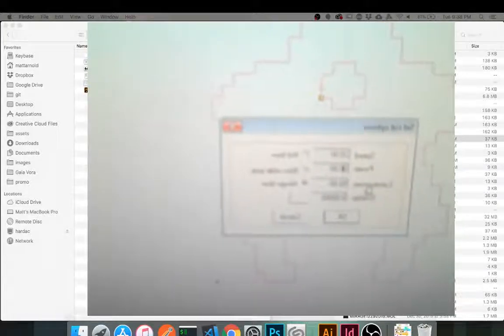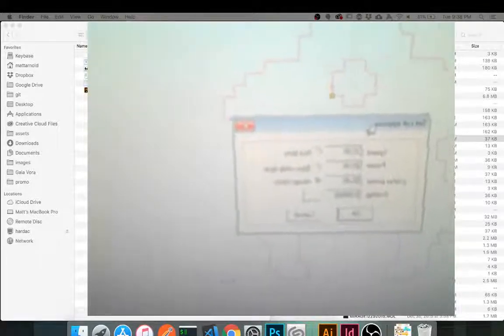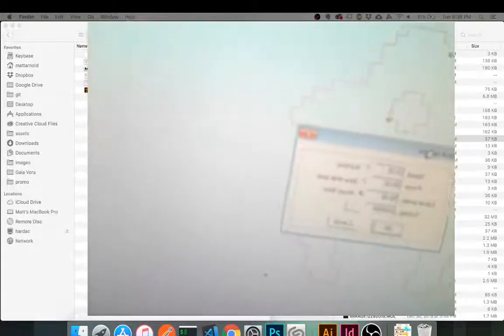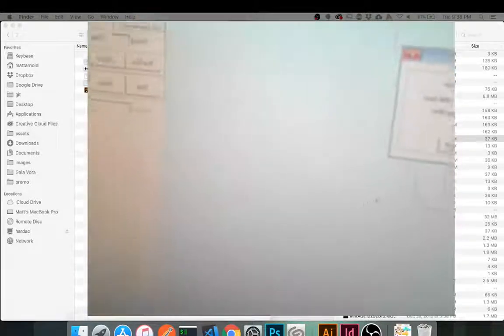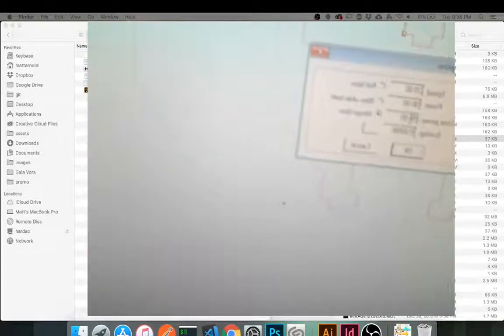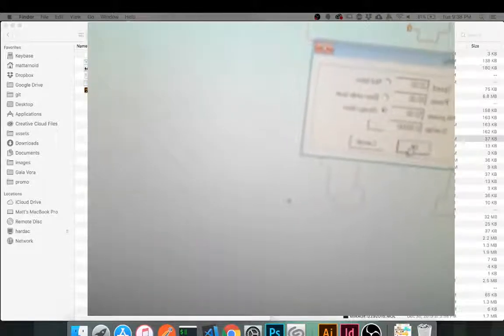If this was a really big piece, I would be concerned about this, because then it's got to accelerate back out of that corner. It leaves a scorch mark. But right now this is such a small little piece that we're cutting out of wood that it's probably not even going to reach those speed differences anyway. I'm not concerned enough to actually give it a corner power. You just give it a little light corner power if you're worried, and that way it won't leave a scorch mark at the corners. So I'll click OK.